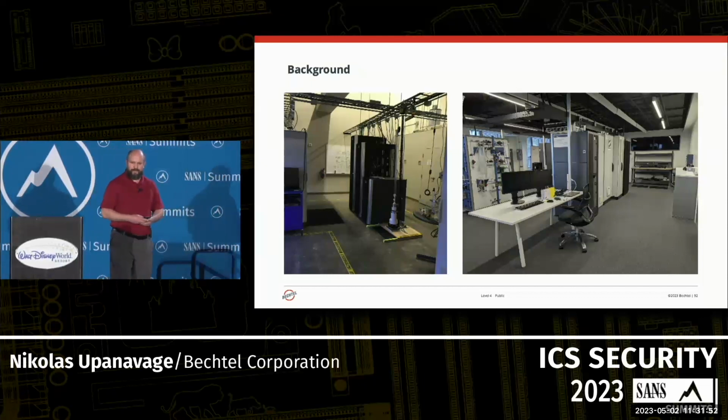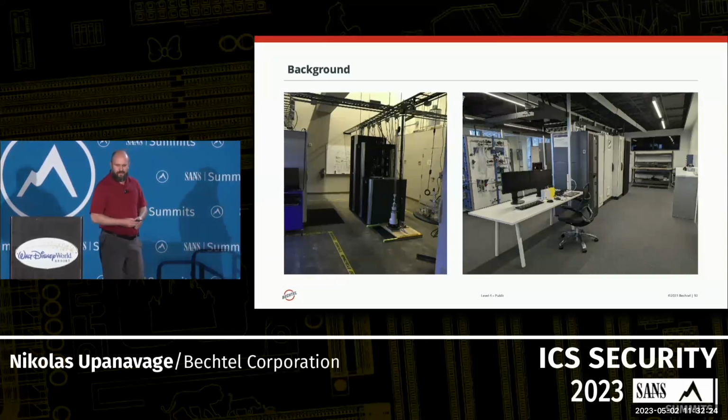The other part of it was, with our existing demo, it's hard to see on the left screenshot, but it was two small little water tanks. We had aquarium pumps, some small level instrumentation. So it wasn't something that you would necessarily see out in an industrial facility. So in the transition we also purchased a trainer skid, and this skid had level instrumentation, flow, pressure, and all instruments and sensors that you would see out in the field.